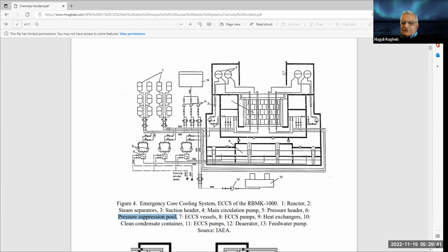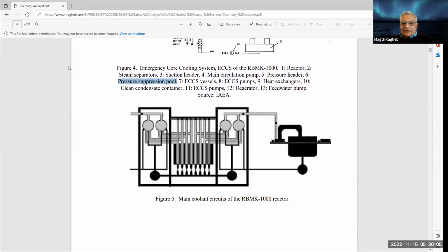It suggests that indeed, when we come back to the Fukushima accident, I'll come back to that argument. Those dark lines here are what they consider to be the confinement structure. And obviously, it was not sufficient to stop the release of radioactivity to the environment. I try to emphasize again that that was a bad part of the design. It was not like the PWR design, where you get the boiling water. It was a boiling light water reactor. In fact, you take the boiling light water and take the steam out of the core. They take the steam here from the steam drum, the same design as coal power plants in general, and that's where it goes to the turbine.